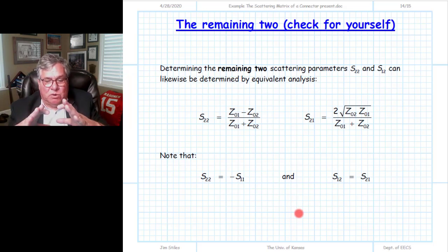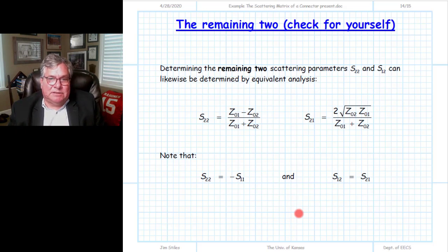The device itself, that perfect conductor, has a plane of symmetry, but the transmission lines that we connect to either side of it are dissimilar, and so they don't have a plane of bilateral symmetry. If we rotate around that plane, we would find that Z01 maps to Z02, and Z02 goes to Z01. Those values are not equal to each other, and so there is no plane of bilateral symmetry.